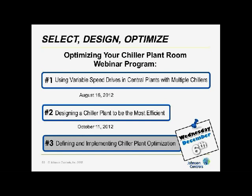Okay. Condenser pumps are variable or constant flow. In the primary secondary system, the condenser pumps were run as constant flow, but we actually were putting VSDs on those pumps to eliminate balancing valves, but they were really running as constant flow. Over in the VPF system, the first VPF in the middle column there, we were running energy-based sequencing without doing anything to lower flow.